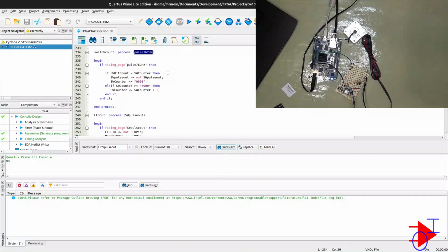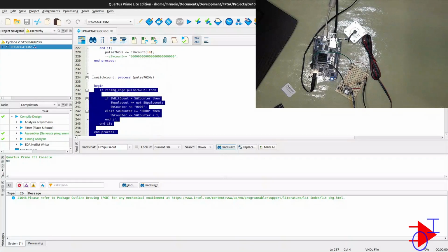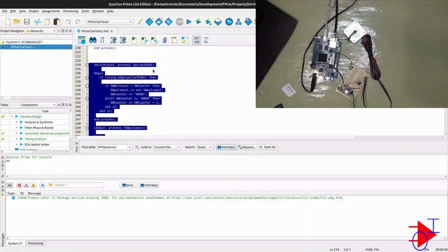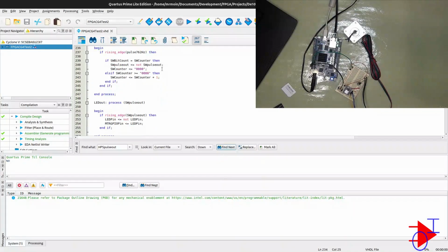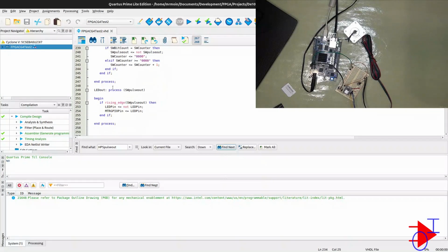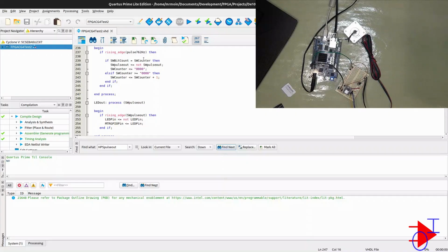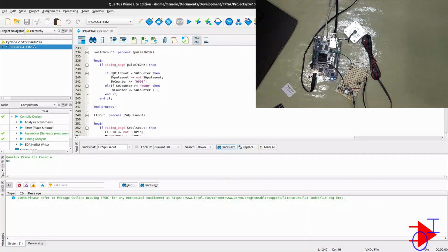Initially, in the first LED example, as you can see, there's an error there. In the first LED example I used the 762 hertz, which is basically a slower output of the 50 megahertz clock. And with that slower output, using the LED, we then slow it down further. Sorry, I take it back. Not using the LED, using the switch, we slow it down further.